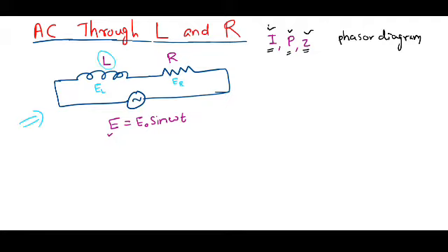We know the phasor diagram in the case of a pure inductor circuit, that is, the voltage leads and the current lags. If there is an inductor, that is L, we have to remember that in the inductor the voltage leads. Therefore, in the phasor diagram, we write the voltage through the inductor, that is EL, that leads the current by an angle 90.